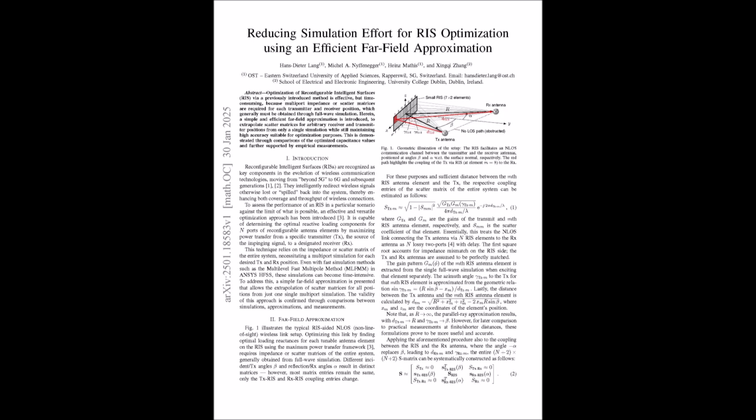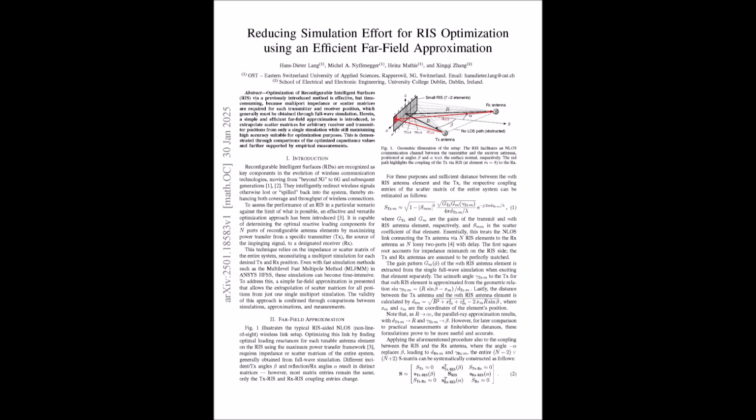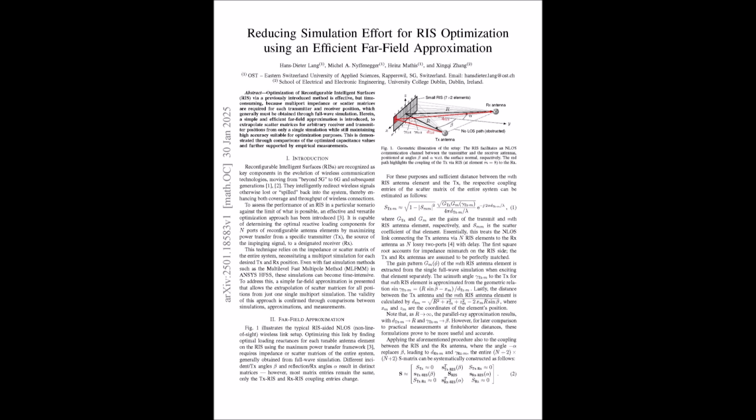Impedance mismatch. Now, impedance is like resistance, right? Kinda, but it's a bit more nuanced. It deals with the opposition to the flow of alternating current, so it involves both resistance and reactance. Okay, and a mismatch means things aren't quite aligned, so we lose some signal strength. You got it. This term helps ensure we're accounting for any loss in signal strength due to those mismatches on the RIS side. But of course, we're assuming that the transmitter and receiver antennas themselves are perfectly matched. Right, so we're focusing on the RIS itself.